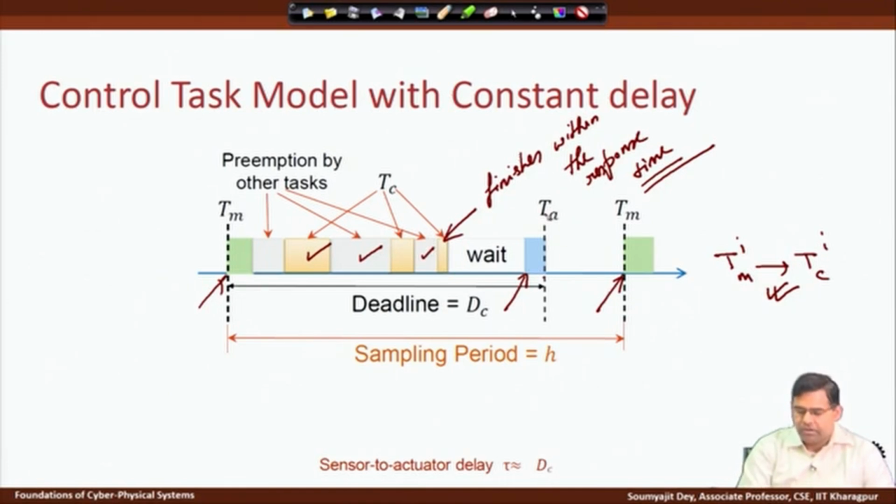But this guy can start because it is event triggered, it will start precisely here only, and that is why we have this wait. In between other tasks may execute and they may be preempted, again other tasks may execute, but the wait is specifically for this control loop, and so the data that has been computed by this control task is still not being processed for actuation, and that is going to happen here.